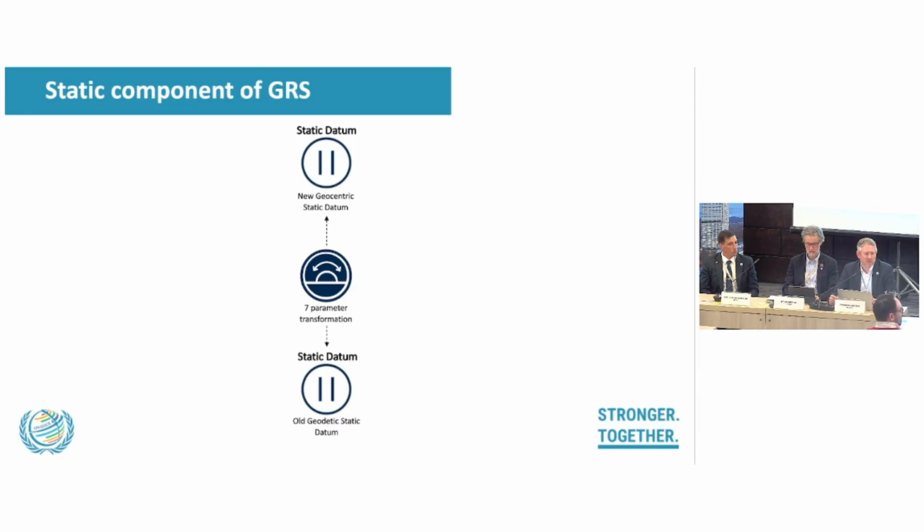So this is mainly in European Netherlands. Almost all data is in the same old national coordinate reference system. It's in meters, with very small distortions because we're a small country. So it's very easy for users to use that. And if we try to introduce something new, in the beginning it would only create confusion and errors. So we only want to do that when we're really sure, when we move to something new, that we'll keep that for at least 50 years, or better even 100 years. And with the current status of ETRS89 in Europe, I don't believe this is the moment to move.